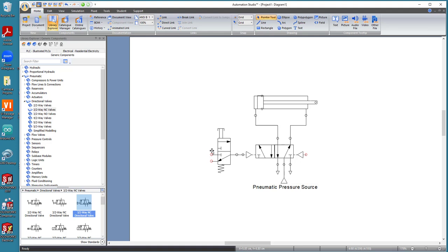So now I need to connect this valve to compressed air, and one of the ports is going to connect to an exhaust. So I need to move this pressure source down a little bit, a little further. So the compressed air is going to connect to this port, which is currently blocked. And so when we push the button, it's going to allow the air to flow into the valve. And then this one needs an exhaust, so I'll just take this.